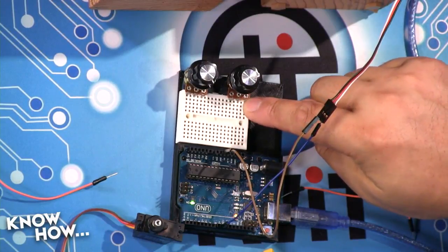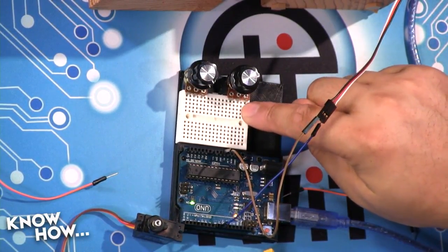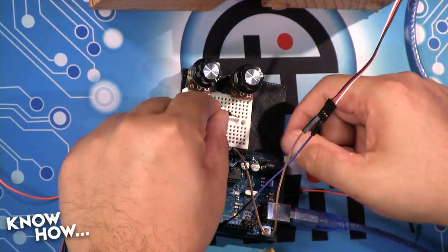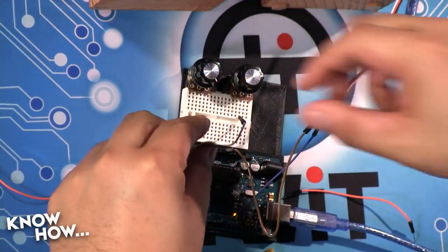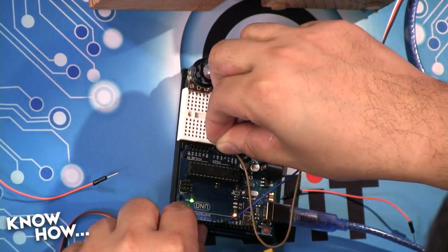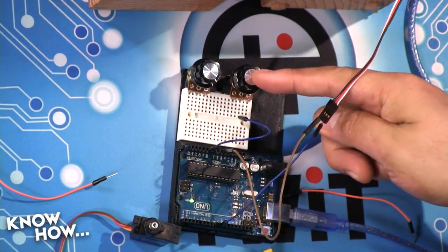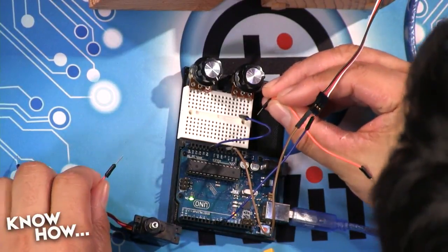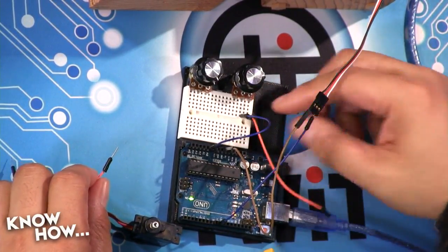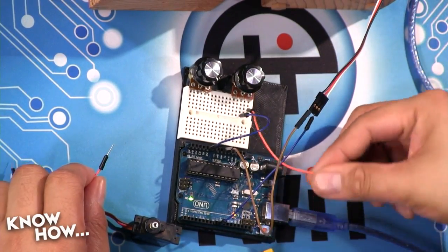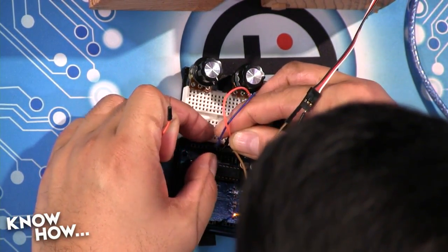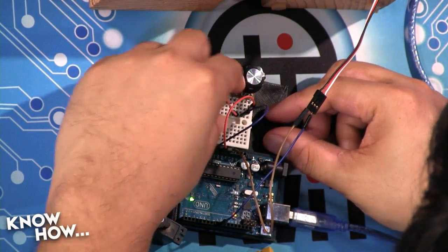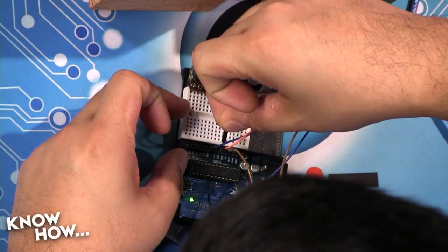So the way that a breadboard works is all the holes across have the same link. So that hole right there is also linked to that one. Got it. So I'm going to go from there to analog pin 0. Cool. So from that to 0, now I need to give this voltage. It really doesn't matter, I can do it either way. I'm going to go here to ground, and I'm going to go from here to 5 volts. Right. I'm going to give it 5 volts.